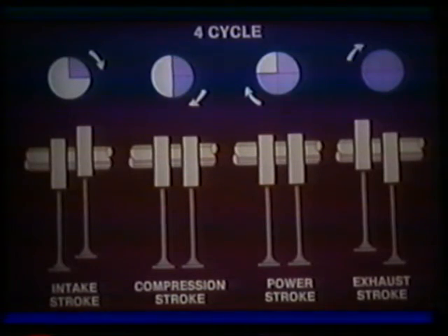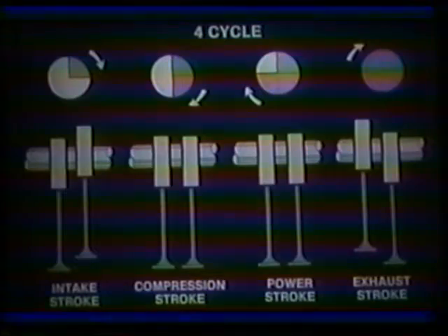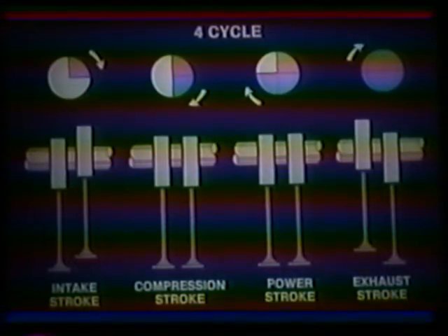While the camshaft is making its first quarter turn, the intake stroke of the piston, the intake valve is fully opened. During the next quarter turn, the compression stroke, both valves are closed. Both valves remain closed during the next quarter turn, the power stroke, and the exhaust valve is opened during the final quarter turn, the exhaust stroke.